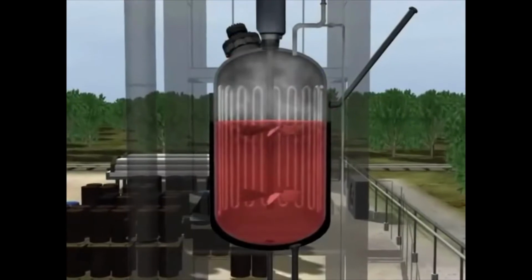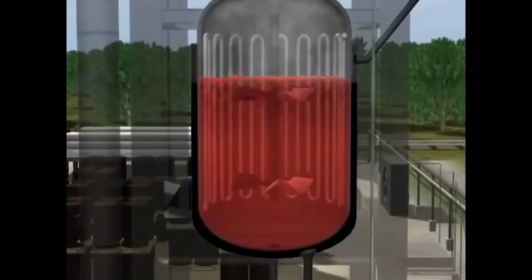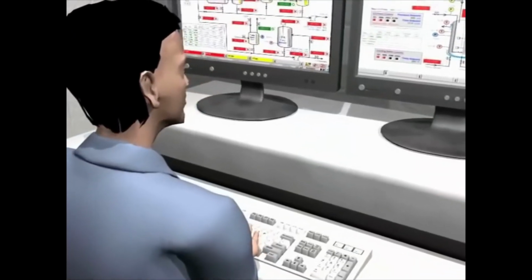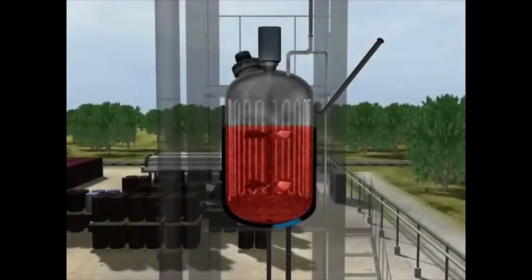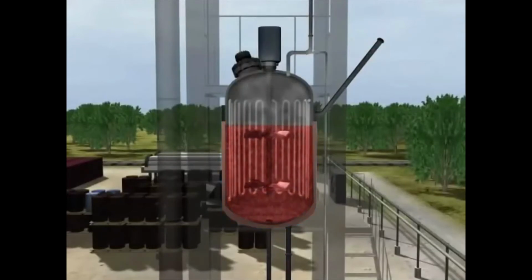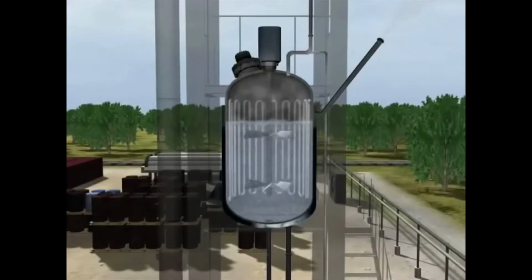During 175 production runs making MCMT, T2 periodically experienced problems, such as unexpected temperature increases, but the company never fully investigated the causes. And T2 had only equipped the reactor with a simple cooling system using city water. When the system malfunctioned, there was no backup cooling immediately available to control the reaction.